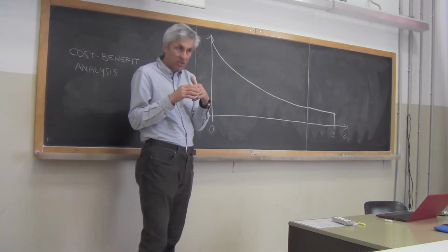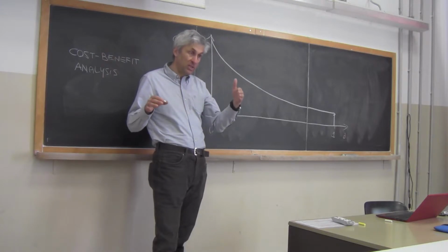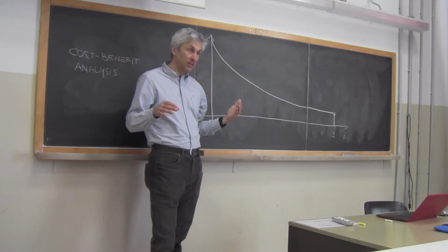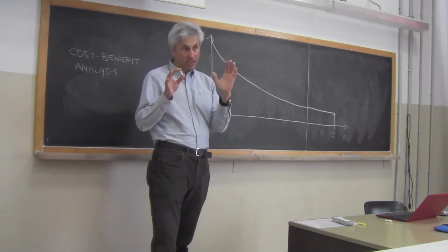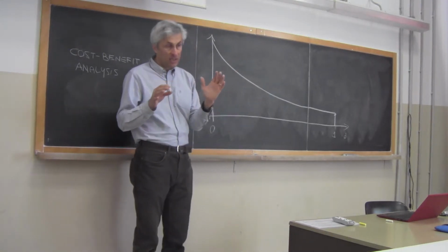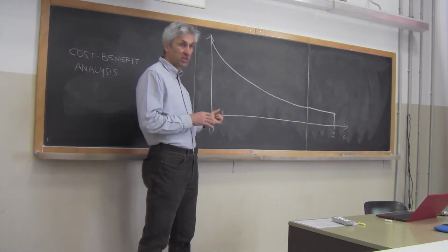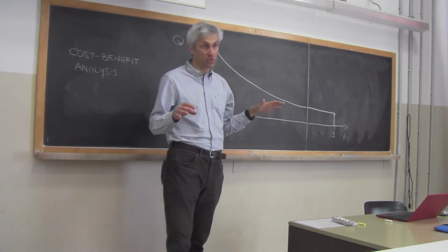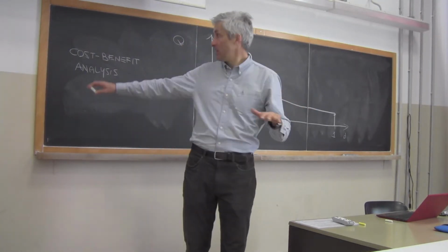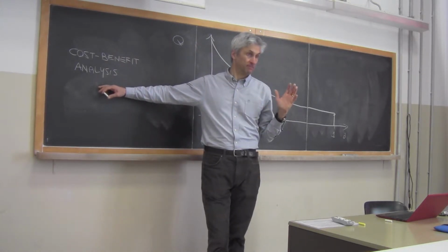And then, as I mentioned to you, the turbine, when it works at a lower flow with respect to the design flow, is not efficient. The turbine reaches the max efficiency when it works at the design flow. So it means that I am designing a plant that works at max efficiency for just a few hours, and the remaining part of the year, very low efficiency. So for sure, if I make a cost-benefit analysis, it's not convenient.